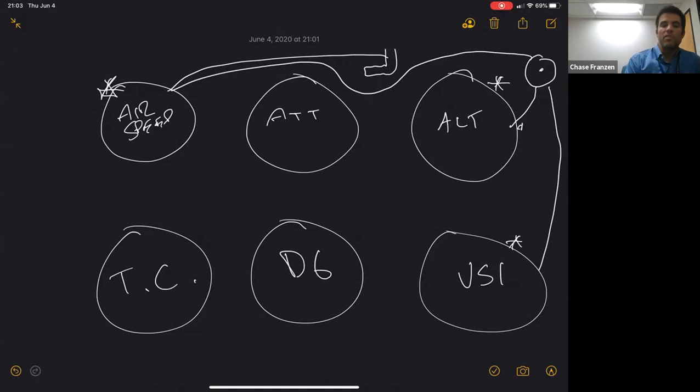As a student, students like to fixate on how fast they're going down, and so they nose over the plane, and instead of looking at the attitude indicator and the altimeter, which react faster, they look at the VSI to know, am I doing 500 feet a minute? But they see it's only 100 feet a minute, and they push over further. Well, they haven't allowed it to catch up to the amount that you're actually descending. And so they end up with what we call chasing the VSI. They've got it nosed over too far, and now the needle goes to 1,000. So now they level out and chase the condition, but the VSI actually lags fairly substantially.